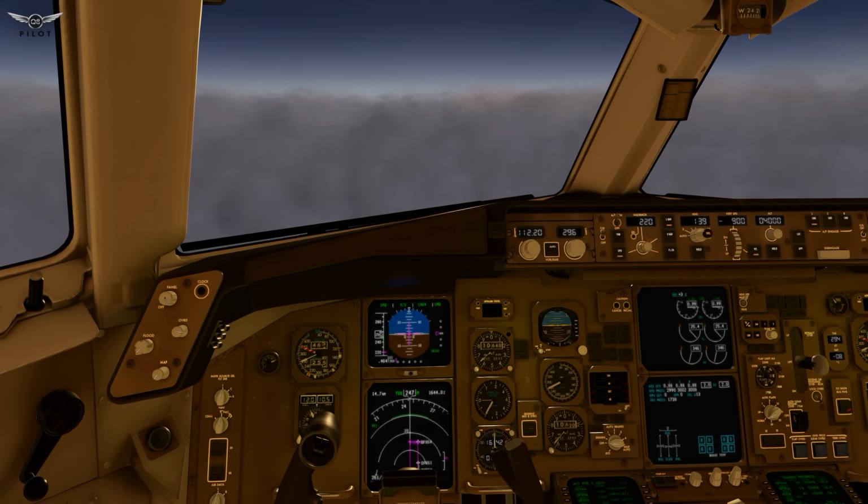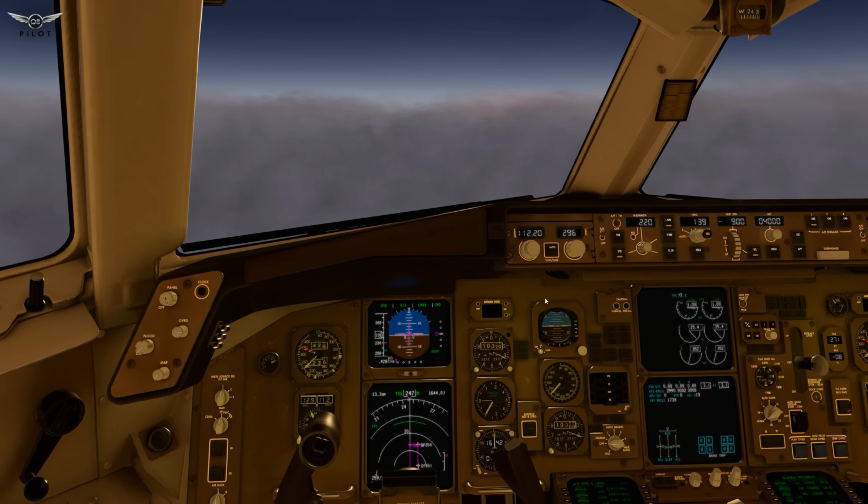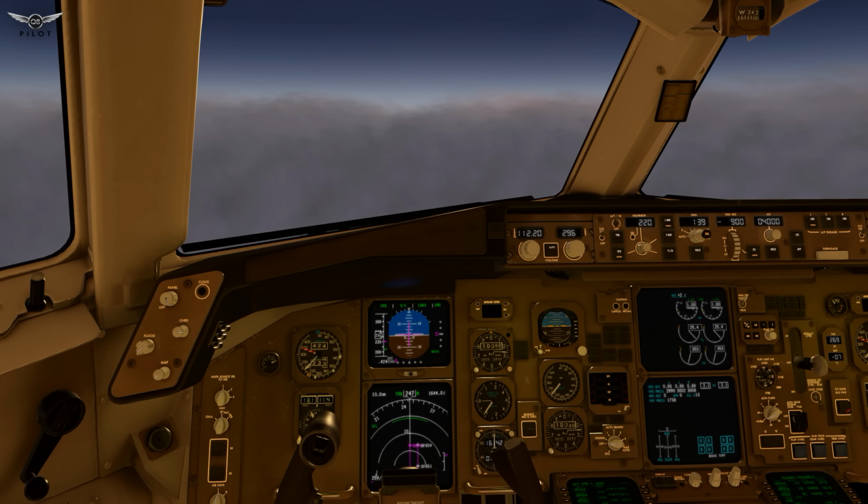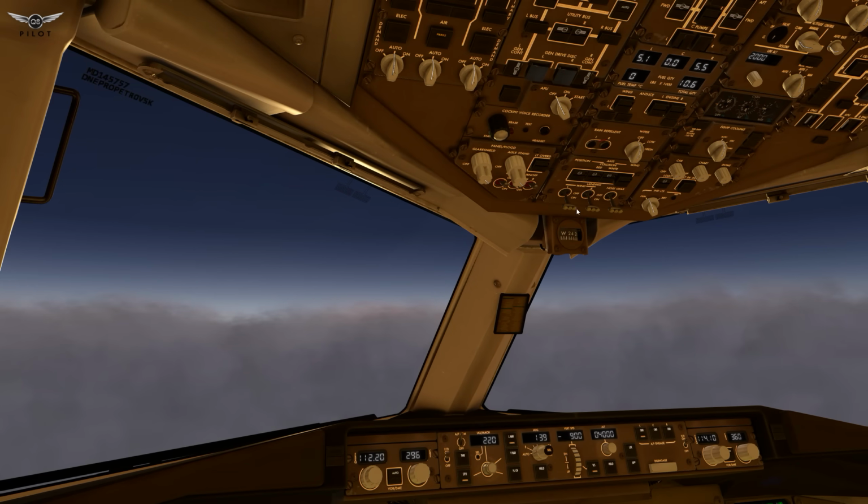We're doing good in terms of our altitude. Alright, here we go. We can now retract the speed brake. And as you can see, we are approaching the 10,000 feet mark. The altimeter has been set to 29.907 or 1,015 millibars. At 10,000 feet, we're going to go ahead and turn on our landing lights.